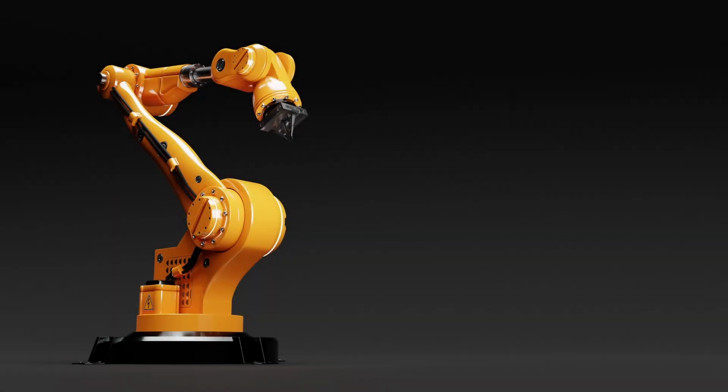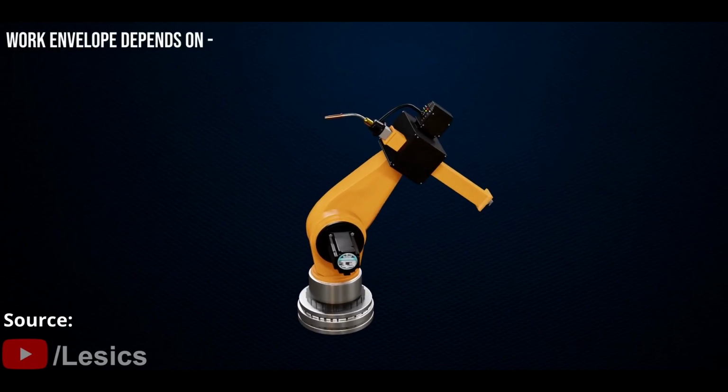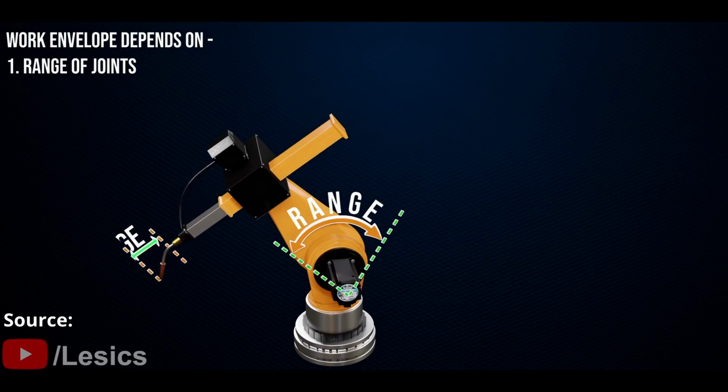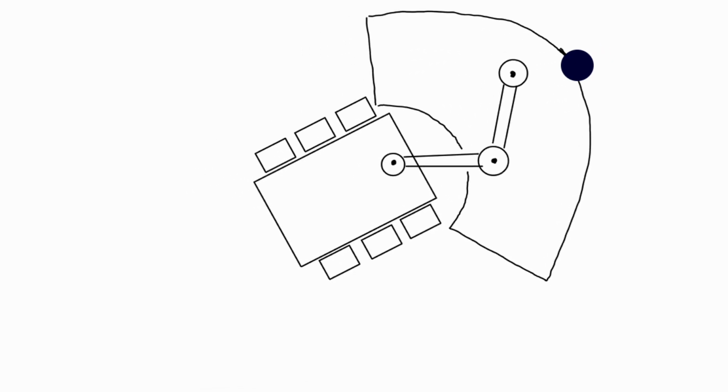Although we said a robotic arm with 6 degrees of freedom is capable of arbitrary position and orientation, it is of course limited to a certain work envelope. The work envelope of a robotic arm depends on 3 main characteristics. First, the range of the joints. As mentioned previously, the human wrist, for example, does not support a full 360 degrees. Of course, the rover can only acquire samples that lie within the work envelope of the robotic arm. If we want to acquire samples that lie outside the work envelope, we need to reposition the rover to do so.